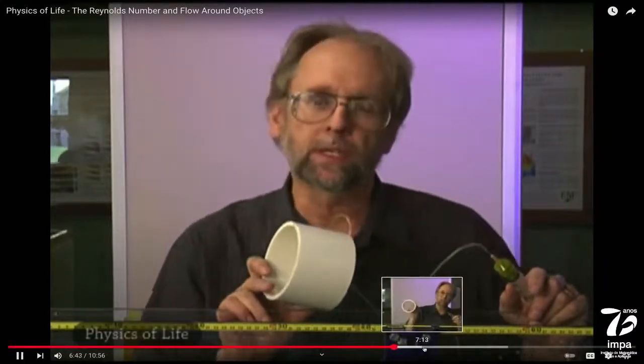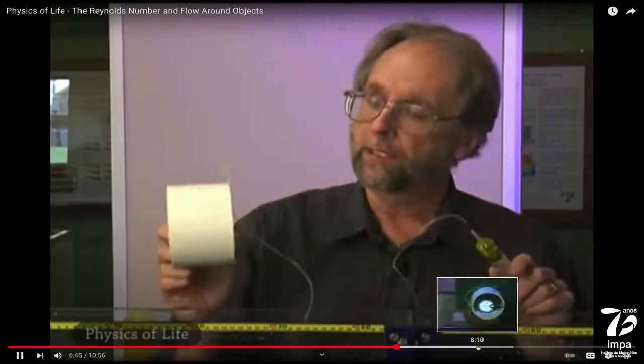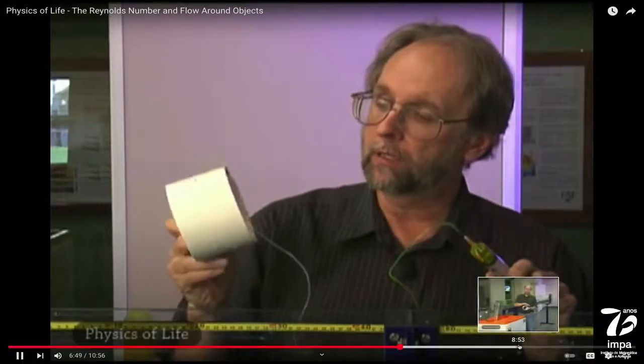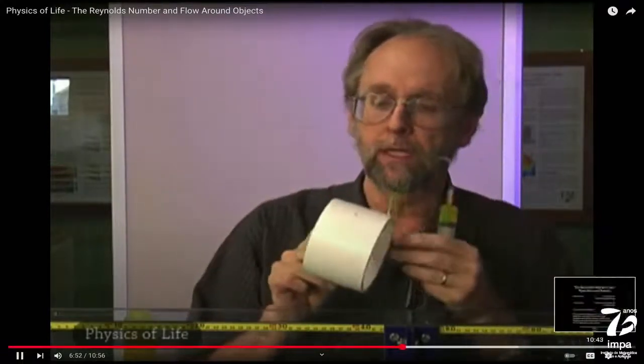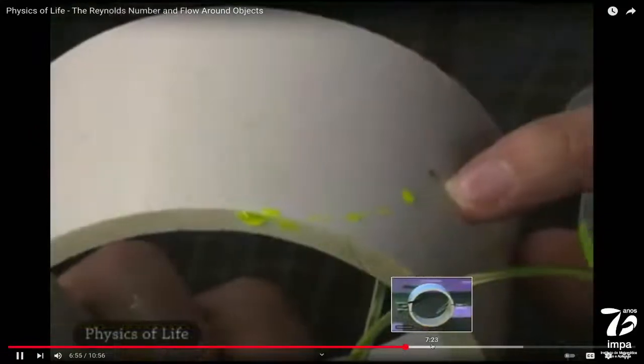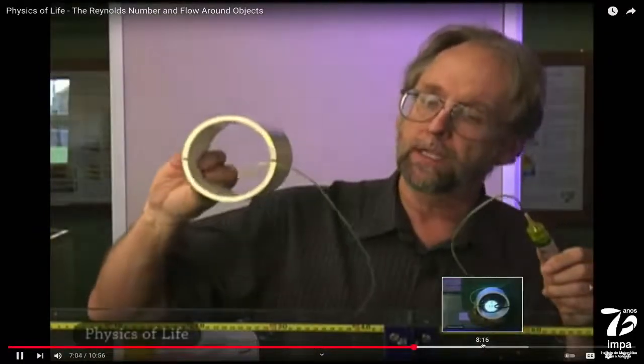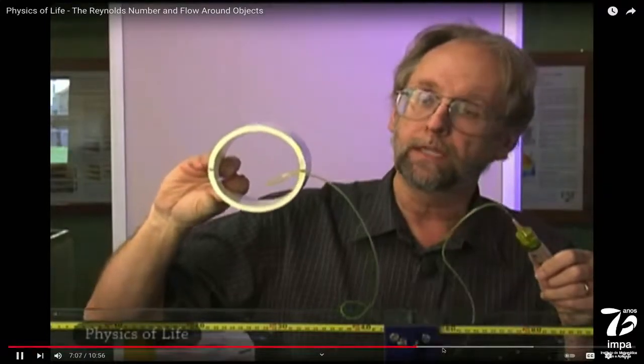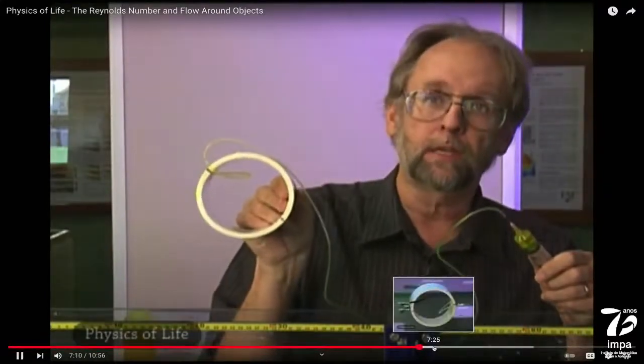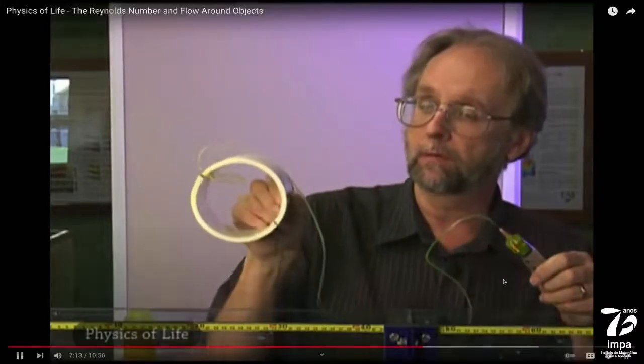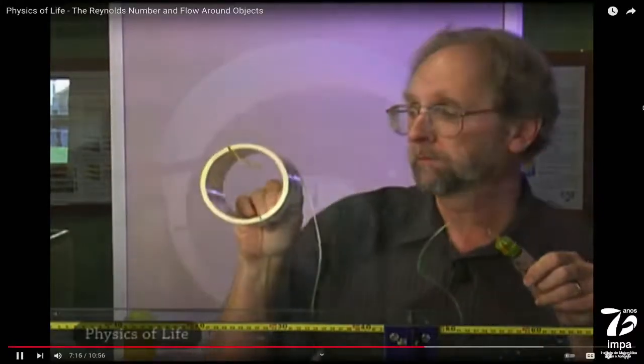We saw at high Reynolds numbers that turbulent vortices are generated at the trailing edge of the cylinder. What we'd like to do now is to look at those flows near the surface a bit more closely. And to do that, we've rigged up a special device. It's a PVC pipe, just like we saw in the other segment. But instead, we now have a little port drilled in the surface of the pipe, where we can eject fluorescein dye. We'll put the pipe in the flume and set it so that dye can be injected at the leading edge and rotated around, so that we can see how flows vary with the position of that port on the pipe.